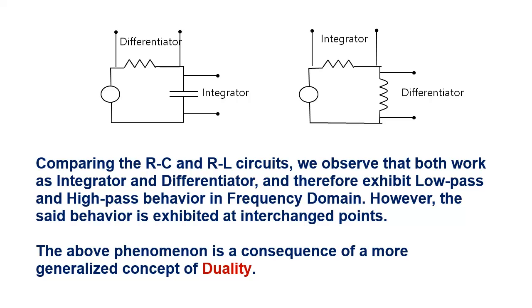Comparing the RC and RL circuits, we observe that both work as integrator and differentiator, and therefore exhibit low-pass and high-pass behavior in frequency domain. However, the said behavior is exhibited at interchanged points. The above phenomenon is a consequence of a more generalized concept of duality.